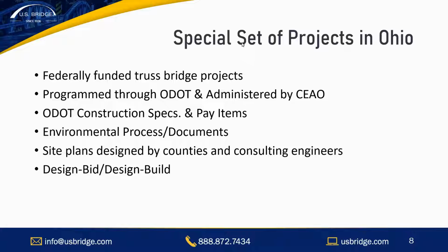So the site plans have everything they need to construct foundations, the abutments, the roadway improvements, cross sections, profile grade, all the pay items for roadways, for foundations, for abutments, but the superstructure details are not fully developed until the construction project's been awarded, and then a contractor taps a design build fabricator to design those plans to augment the original plans during the construction phase.